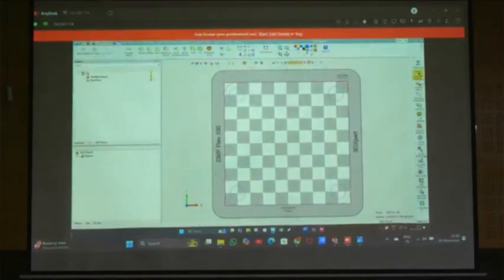So we can add the component. 3D Expert is the slicing software for the 3D Systems machines. Since we have a DMP Flex 100, which is supplied by 3D Systems, they have given the software 3D Expert to generate the tool path to put into the machine, so that we can slice the 3D model. We can see that now.